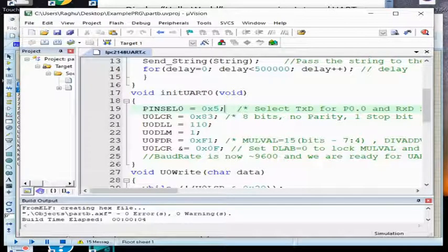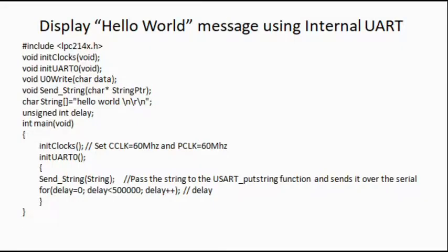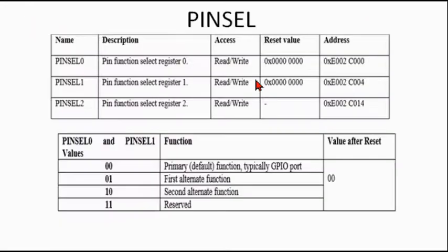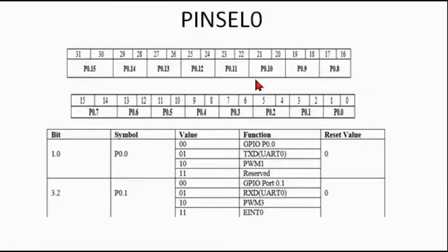We'll see here in the PowerPoint, sorry, microcontroller manual. See here, P0.0, I want to use it as a TXD.